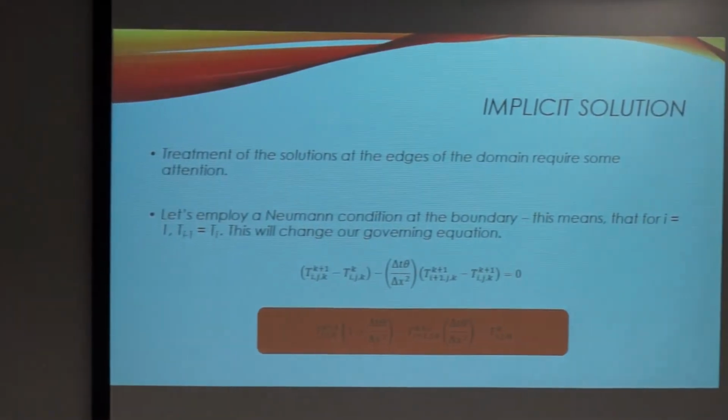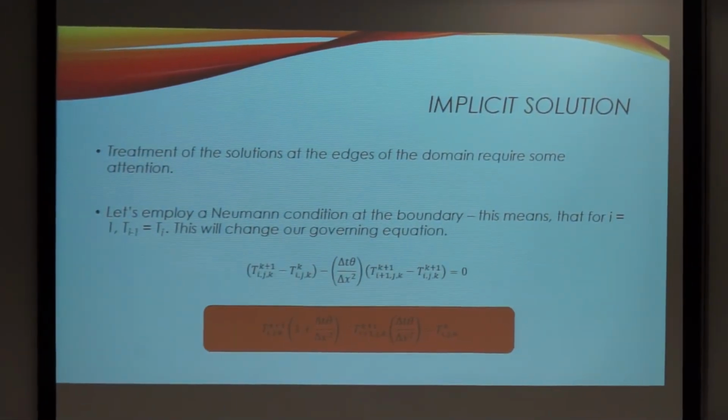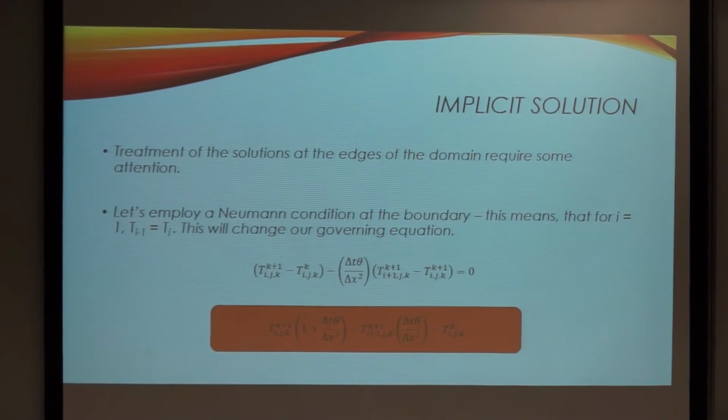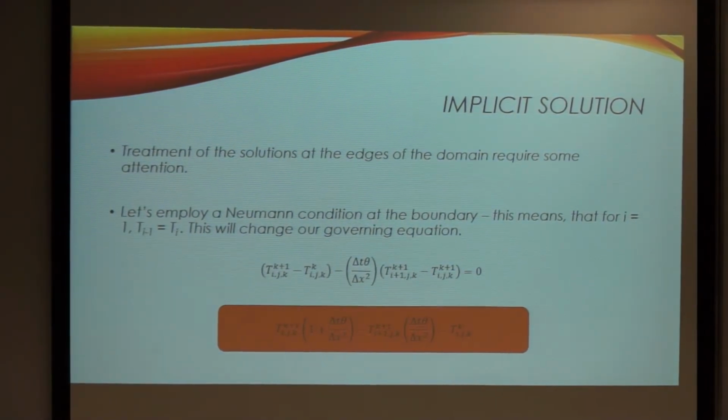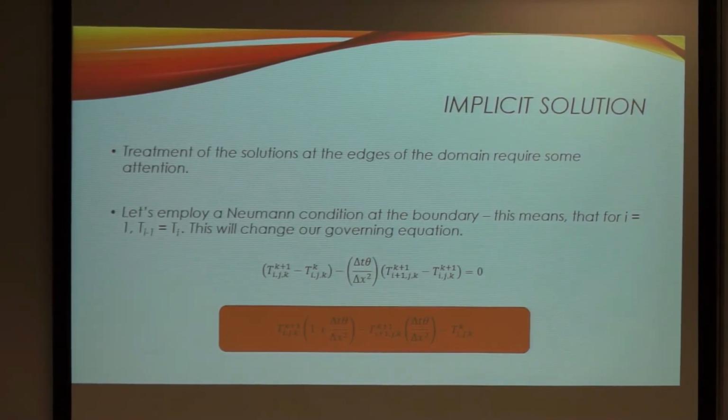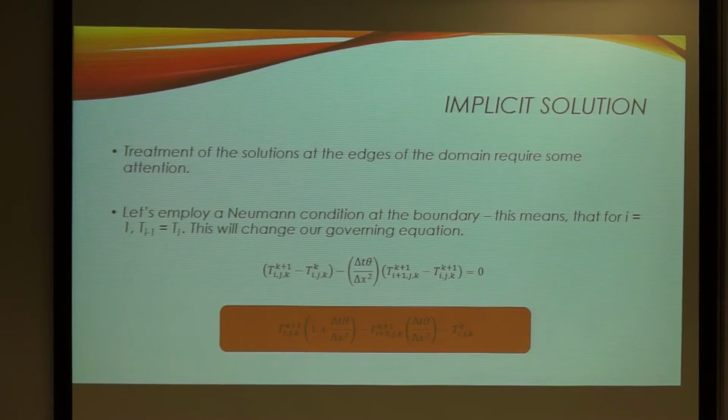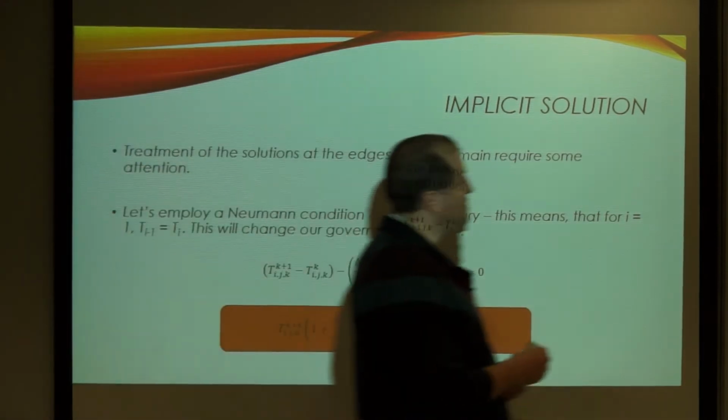However, if we just build it like this, we still have the same problem we had last week: boundary conditions. You might remember from last week using FTCS that the boundary conditions were very, very important. We basically have two kinds of boundary conditions. Last week I talked about them: we had Neumann, that's a zero gradient or a specific gradient, and we had Dirichlet, where you set the temperature to be whatever you like. Let's talk about Neumann at the boundary. If you weren't here last week, I'm going to tell you now anyway.